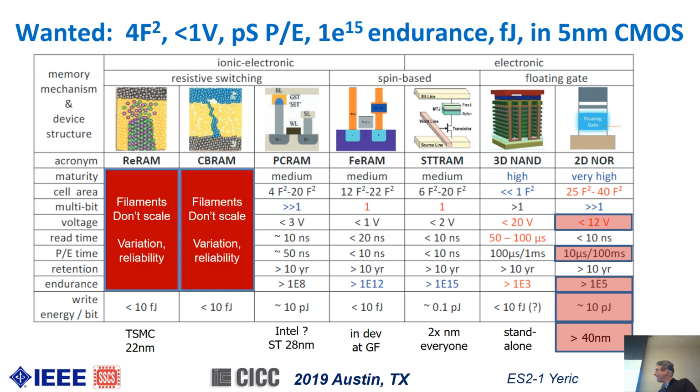I'm not a big fan of the resistive memories. The filaments are just too stochastic, and the reliability is too low. Right? You can't use that from a logic perspective. Though you can get it from TSMC now. You can get RRAM, I think, at 22 nanometers. It's a lot better looking than the flash type technologies for embedded. But from using it in logic, I just don't see it happening unless there's some really big fundamental improvements in the various technologies.